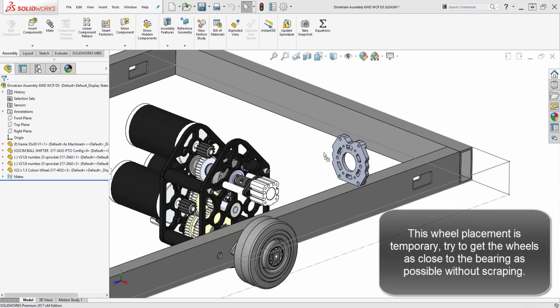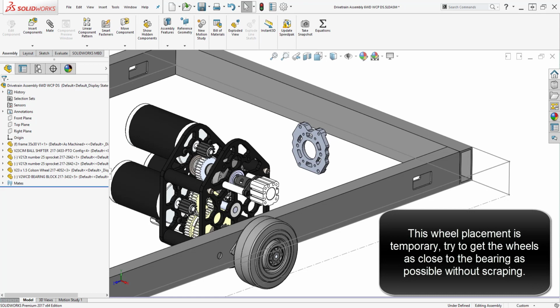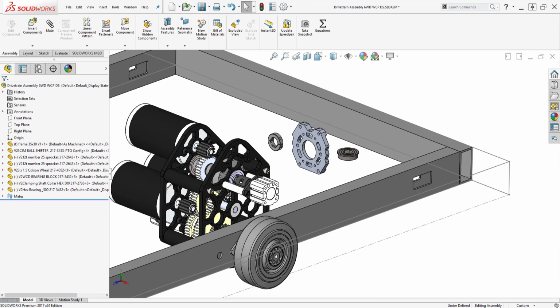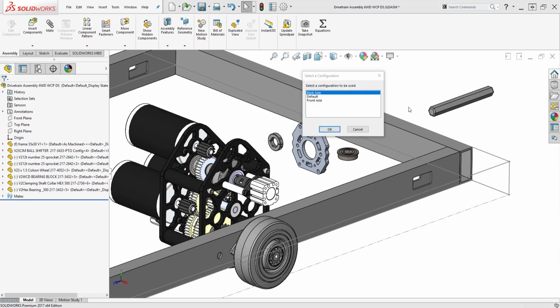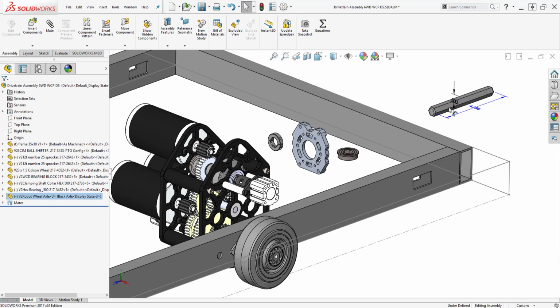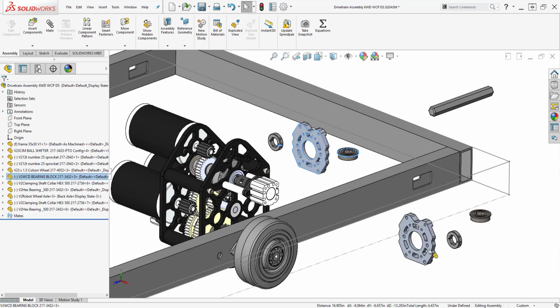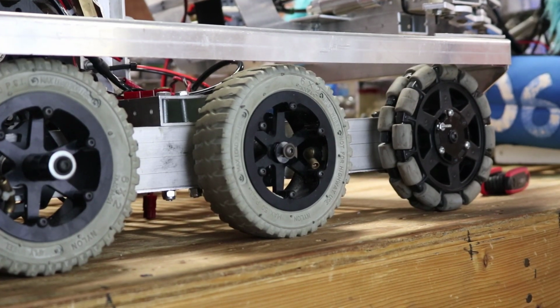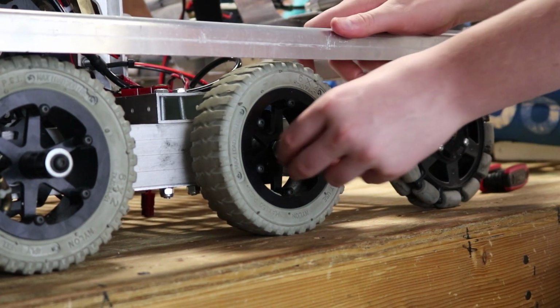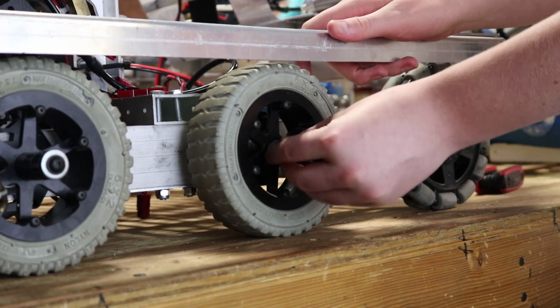Next, we will focus on the back of the robot. We want the back of the robot to have inboard chain positioning because our design called for more space up front for components, so this is how we decided to do it. This axle for our Colson wheels needed to be 4 3/4 of an inch long, but your axle length is going to vary depending on the wheel. Many teams use shaft collars, so we have included the length required to make that happen in this CAD file.